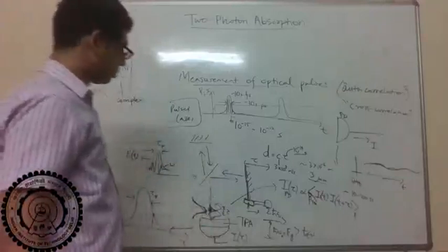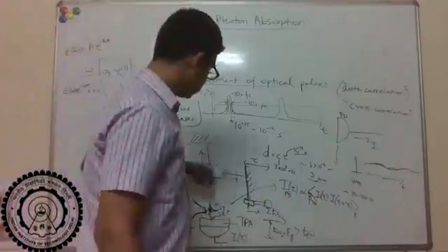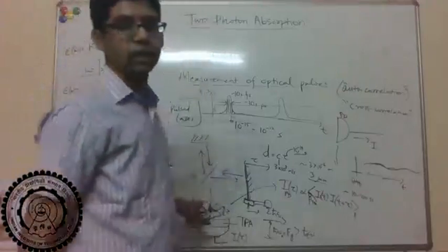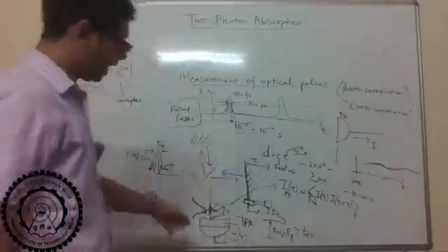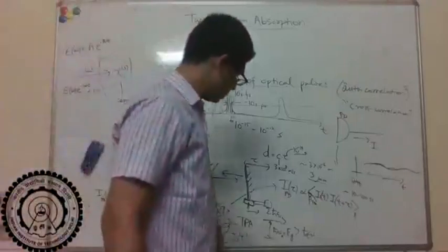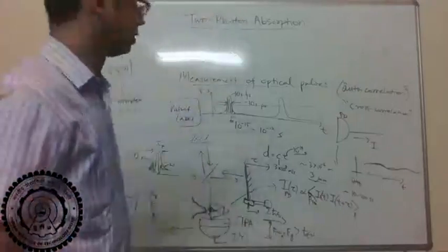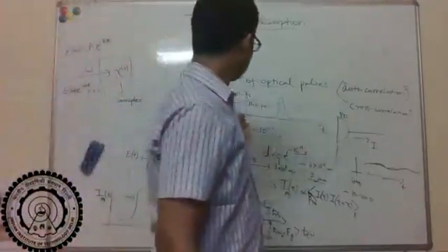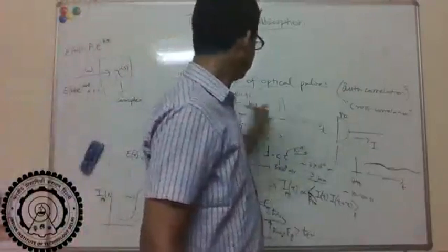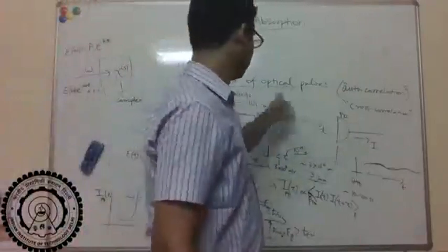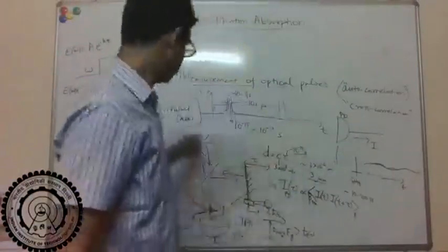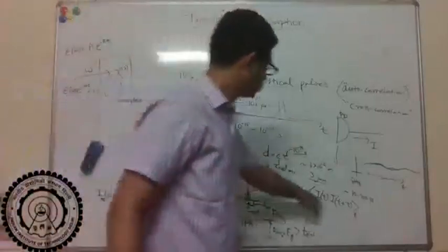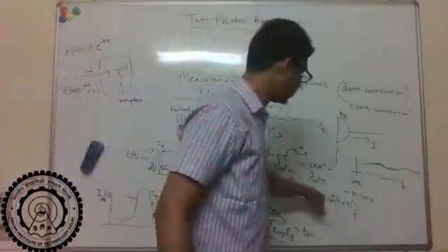Right, so basically, the interferogram between the two signals depends on the delay. As I change the delay, my average photodetector output is changing. Whereas if I just directly detect it, then there's no way for me to recover these pulses, even if I delay or whatever. I need something which goes as the product of, or something which goes as I squared.